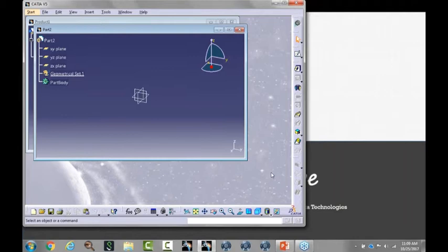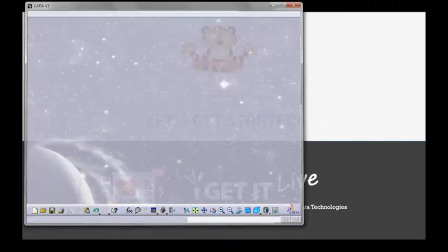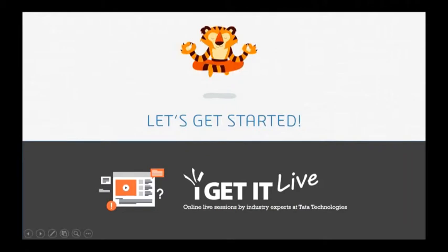So number one, that splash screen. Let's get rid of that. Now, these used to be called secret environment variables. When you initialize CATIA, what happens is it reads a file that has all of the variables in it that are important to CATIA. Then when you make changes, those changes are annotated in what's called CAT settings files. So you have a group of files that actually remember the modifications that you made.